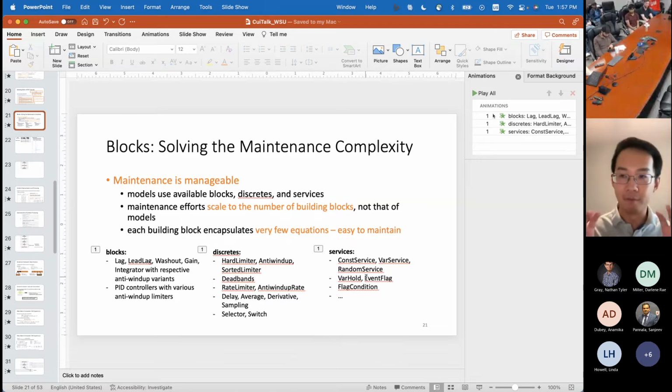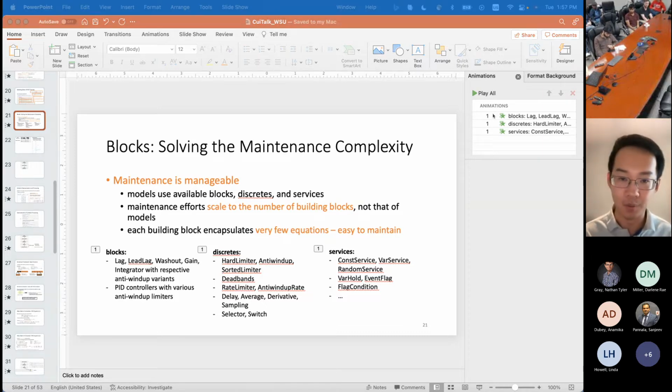But in terms of validating the phenomenon, we need to first check that each individual model is implemented correctly. To me, that is ongoing work because it is very difficult to validate every nit and bit in that converter model. There's a lot of logic in there, and now it's done by hand. But I'm thinking about ways to automate those tests, for example, a governor step response test or exciter step response test.